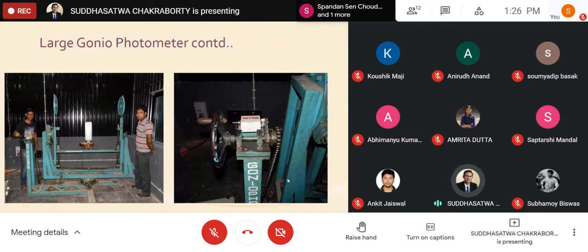That is a new one we bought a couple of years back, which is functioning very well. But the issue is that here you don't have that much manual intervention. It will do it automatically, it's a robotic sort of thing. There is an arm, and you just use a laptop with a dedicated program. You set the ranges you want and it will automatically take the data. The robotic arm will rotate the entire luminaire up and down and left and right, and accordingly record all the data instantly. So it is fully functioning and fully automatic.